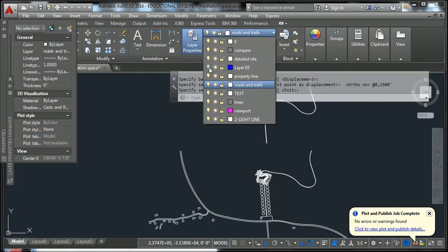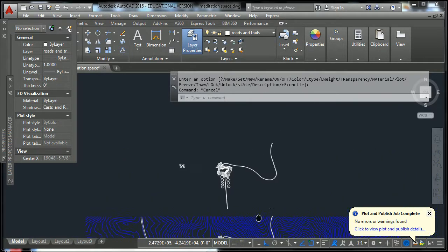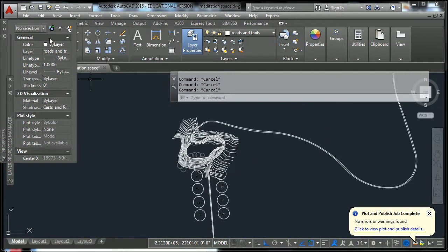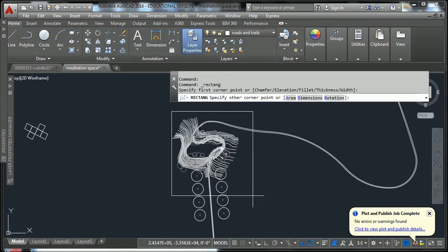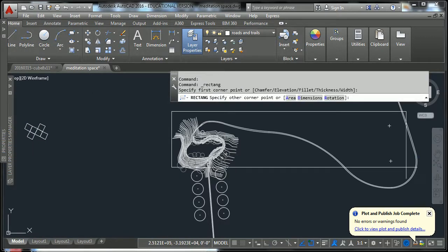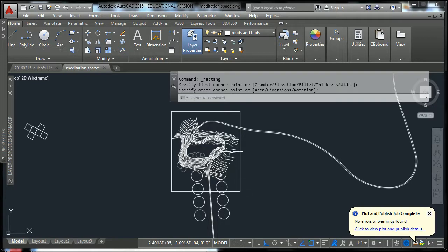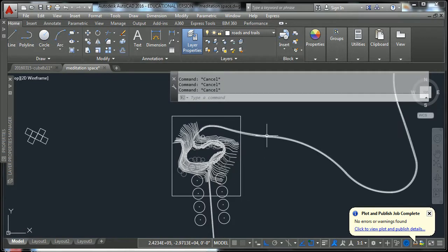You can now even turn the topo back on again, because all we're doing is using this. You can go ahead and draw a rectangle around this thing, because we don't need all of these roads. So we'll get an area that's somewhere close to there, and again, it's not that scientific right now, and we'll use this as a trim line.